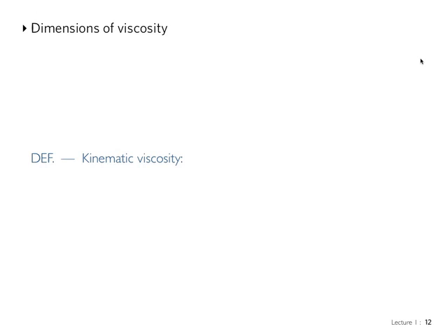Okay, the dimensions of viscosity. Recall, this is the equation that we introduced for viscosity in the case of Newtonian fluids. Remember, this is particular for the case of Newtonian fluids, where there is a linear relationship between the shearing stress and the rate of shearing strain. So what are the dimensions of tau? Well, we said tau is equal to force divided by area. So force is, in just dimensions, let's just use force and length squared for area, without introducing units, just dimensions.